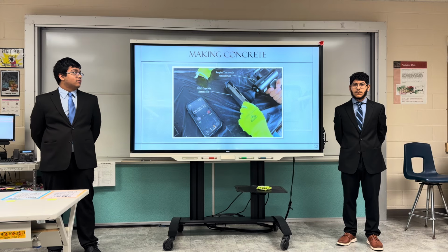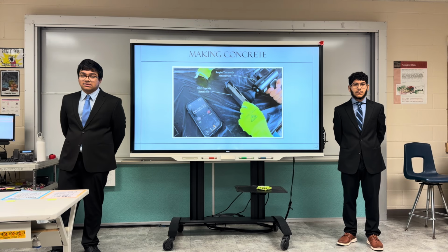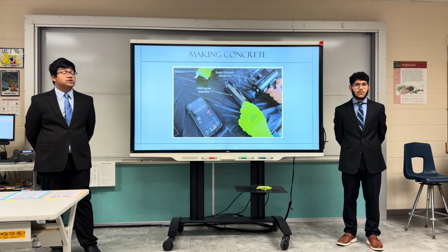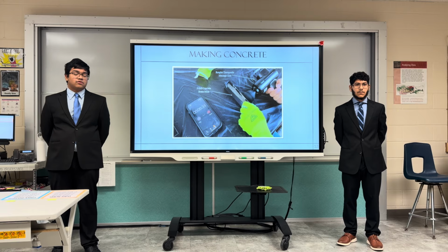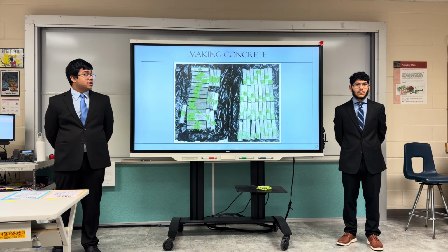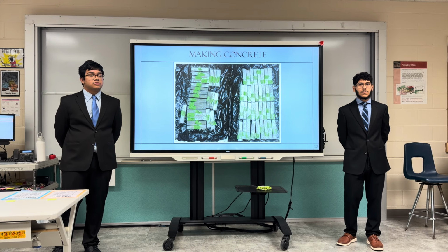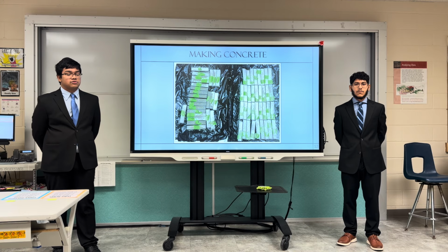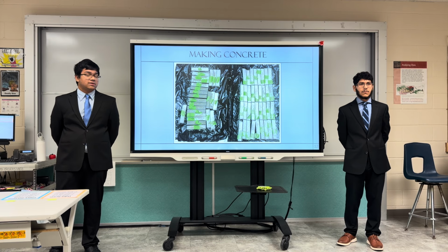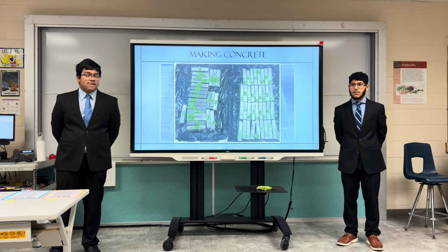After our mixture was fully formed, we poured it into a mold, then used a massage gun to settle it, and then a trowel to smooth it out. 24 hours later, our concrete was dried, and we used a simple random sample in order to assign treatments to each beam, 30 cured, 30 uncured.